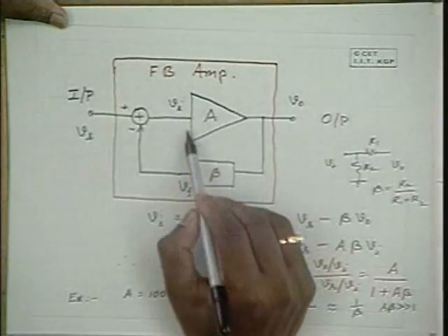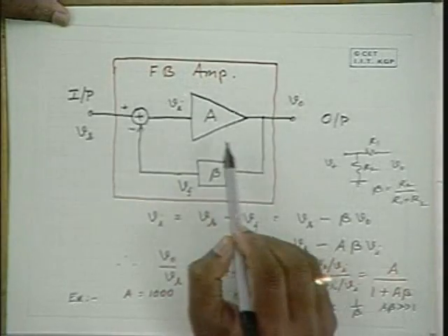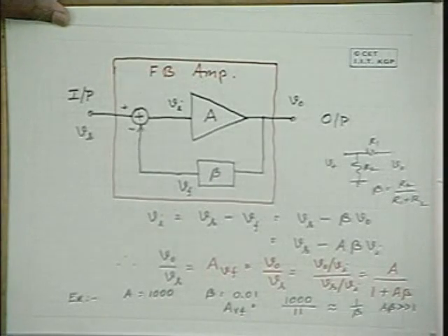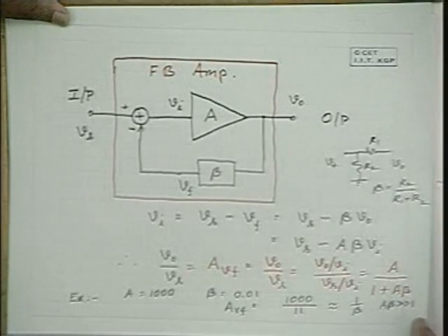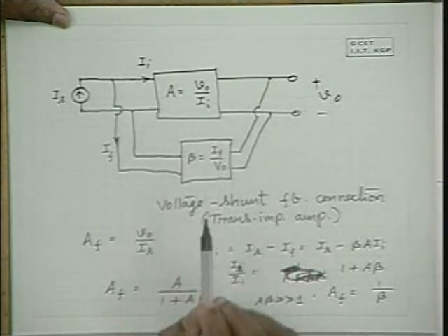and the amplifier involves active elements. Therefore, it is not stable because different amplifiers with different transistors exhibit different amounts of gain. The HFE may be 100 in one transistor. If you pick up another transistor, it may exhibit an HFE of 50. So HFE, or beta, directly gives you the current gain. So here itself there is a difference in the current gain. Therefore, different amplifiers may exhibit different amounts of gain, and in the process of feedback, you are making it independent of the amplifier parameters, and you are making it a function of the more stable feedback network parameters.